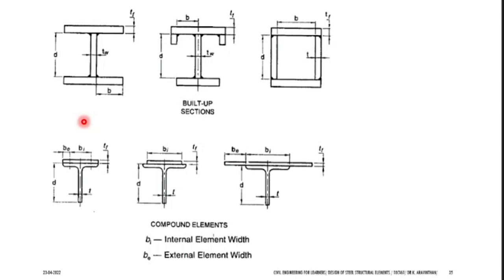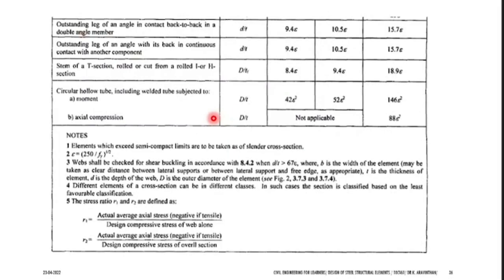So those kind of beams are not available through any supplier. You have to purchase the plates, build it on the site or in the shop. So you can do these kind of sections. These are all known as built up section. Take a channel section. This you can observe that this is a channel, that is C section. You have a plate and another plate. With the 2 plate and channel section, you can make a built up section. Okay. These are some of the examples.